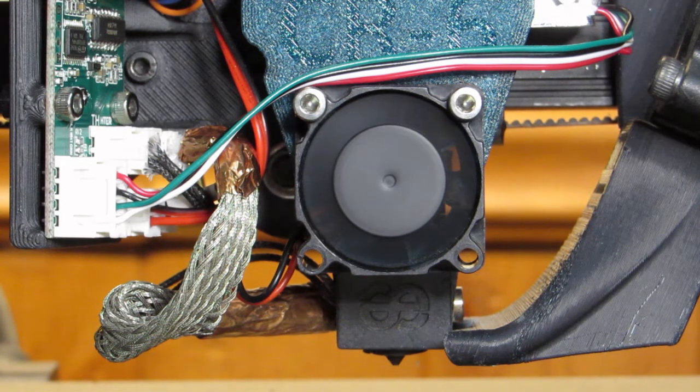the other risks. Don't clip your wires together on the nozzle. It pulls at the hot end. It pulls them all towards the daughter board, which leverages the diving board upwards and predisposes it to triggering. Don't mess around too much with RP1, because as often as you do that, you change whether the gauge is even working within its linear range. You don't know that the processor has enough margin in the firmware to tolerate you moving things around in the settings outside of Creality's design limits.